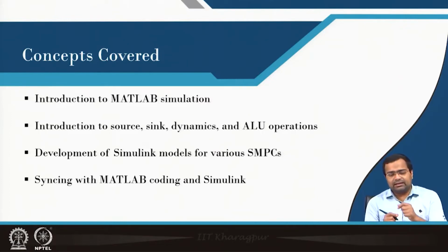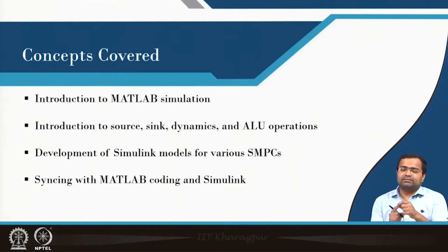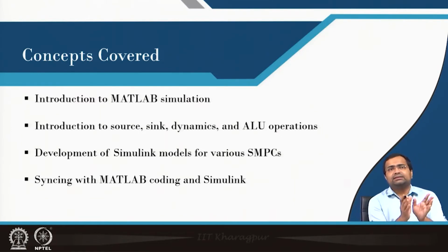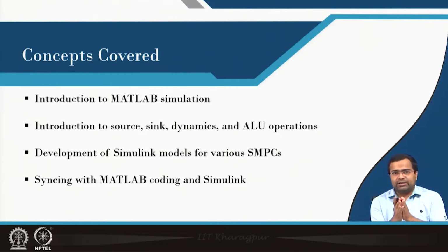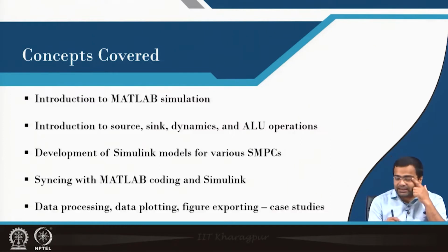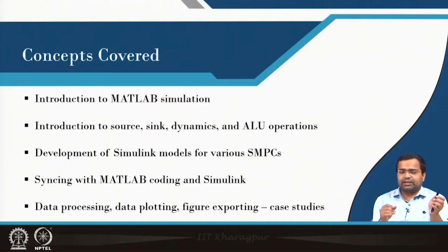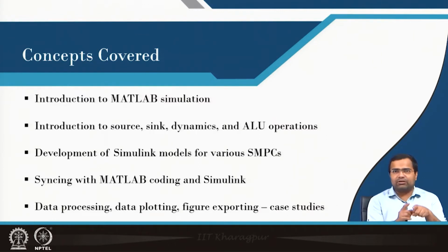Then syncing, that means synchronizing MATLAB code and Simulink, and finally, I will also show how to process data. That means, if we see the scope simulation result which does not look good, we need to take those data into the workspace, and then from the workspace we need to plot it, and we have to create according to this axis command, and then we will show some case study simulation.